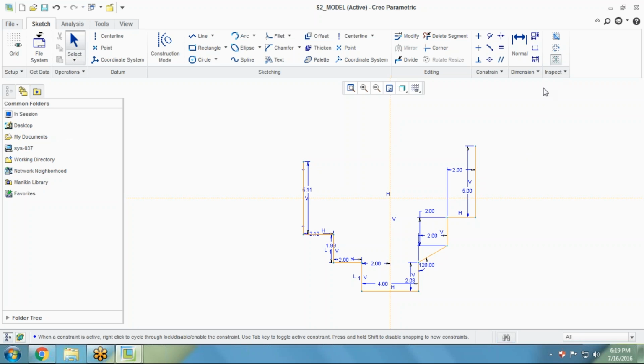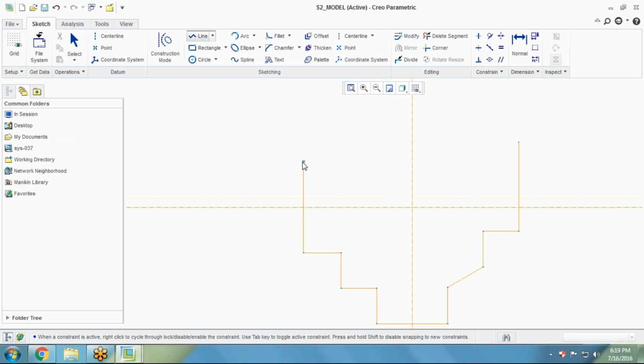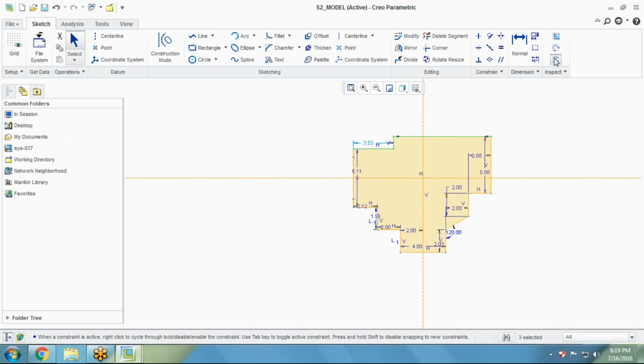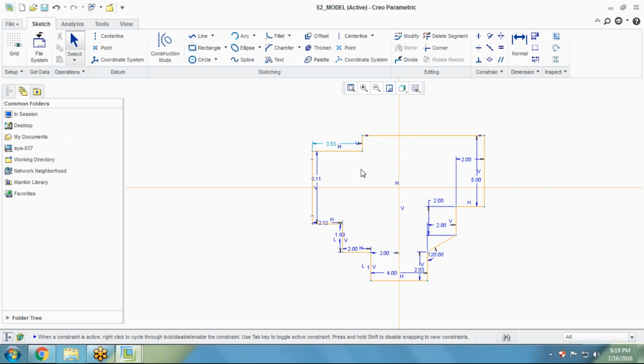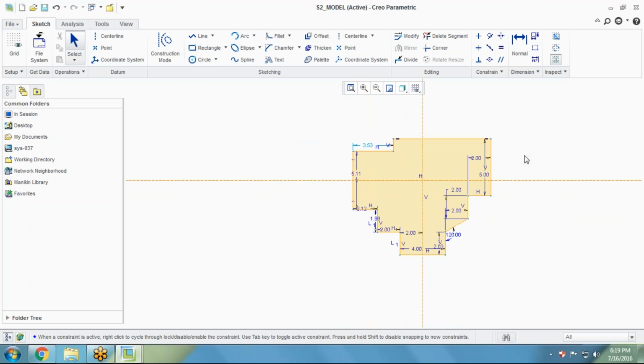After that we can see there, if the geometry is closed, you see, if I'm just closing the geometry 1, 2, and now I'm just clicking at this point. So you'll see there, the geometry is closed, but it is not showing you that this is a closed geometry. So if you want to make it show, just go on the shade close loops. So the loops will be shown to you in the shaded modes like this.